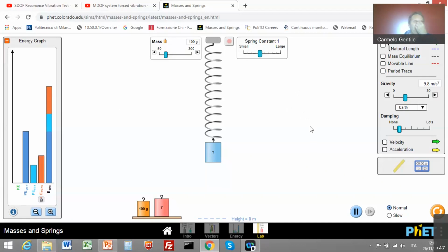So, for example, a nice choice is to build a very deformable building on a rock soil and a very stiff building on sand, because if I build a deformable building on the rock, the motion of the rock is rich in high frequency, while a deformable building has a significant response for lower frequency.